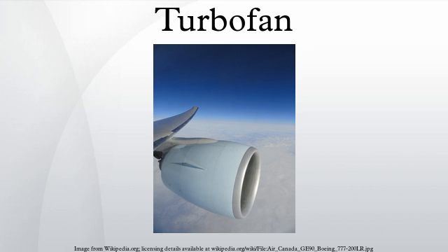Most modern American civil turbofans employ a relatively high pressure ratio high-pressure compressor, with many rows of variable stators to control surge margin at part throttle. In the 3-spool RB211/Trent, the core compression system is split into two, with the IP compressor, which supercharges the HP compressor, being on a different coaxial shaft and driven by a separate turbine.